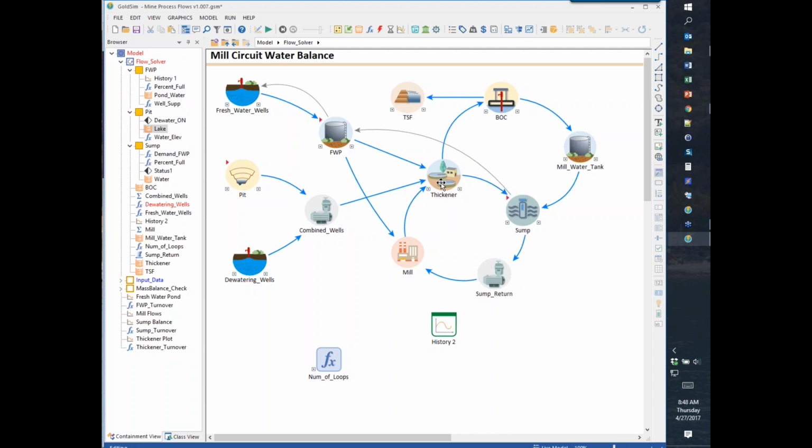And so what we would have to do is make the time step quite small. What we were doing was probably around 5-minute time steps for it to work, and that was because the residence time in this clarifier was about that. It was something less than an hour, I remember. And so having very small time steps worked just fine with the weir equation at the clarifier.